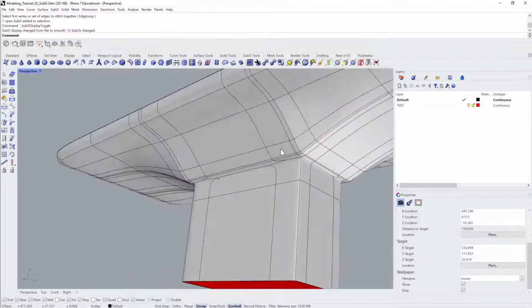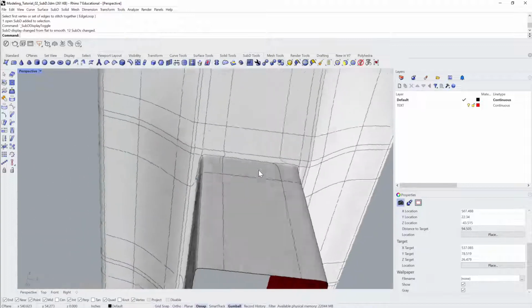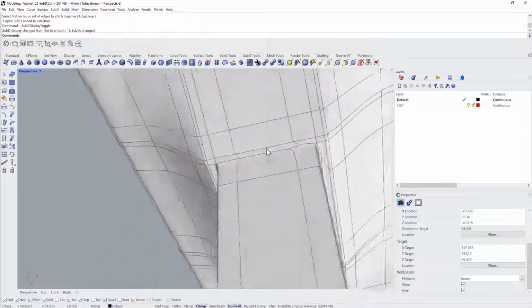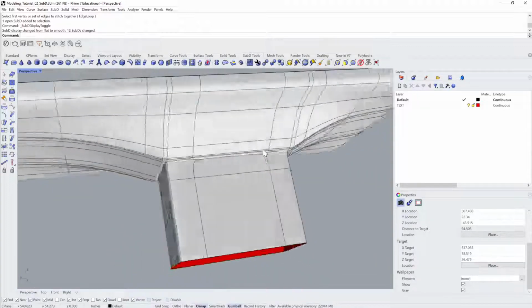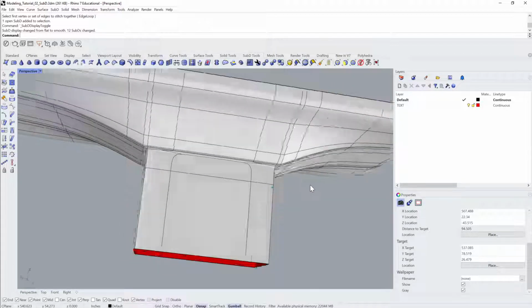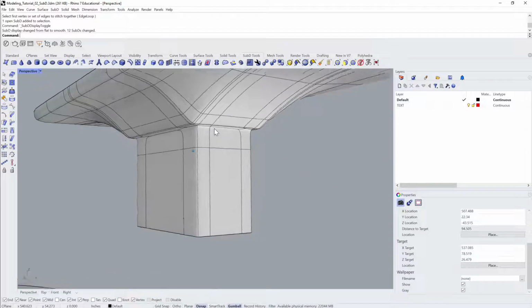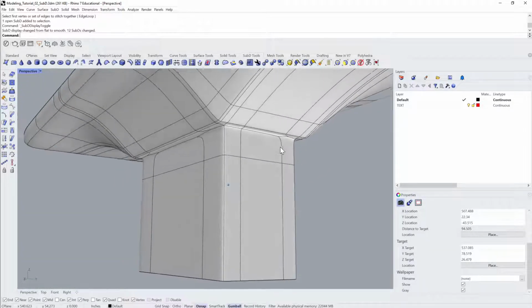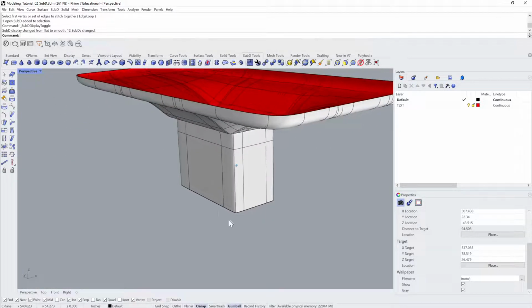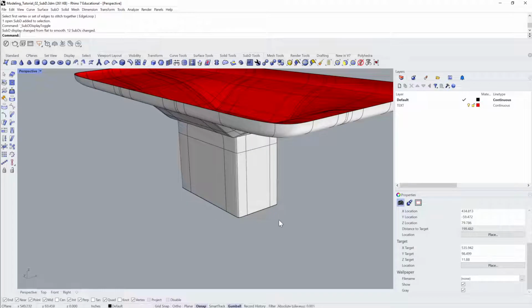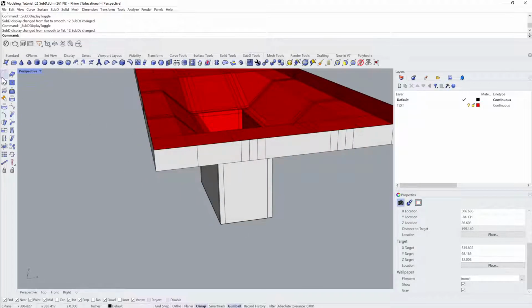That looks like what we want to see, where I can just tell that things are pushed together in a good way. So the way that I modeled this was a little goofy, and it wasn't stitching the vertices together. But you can always link things together with this command called stitch.